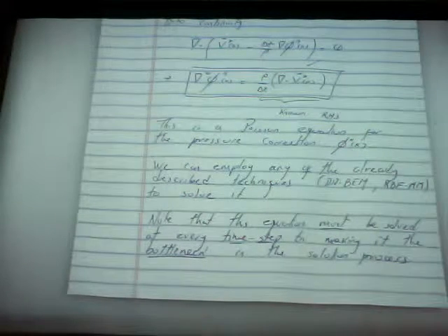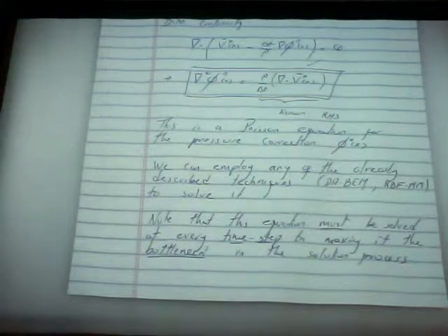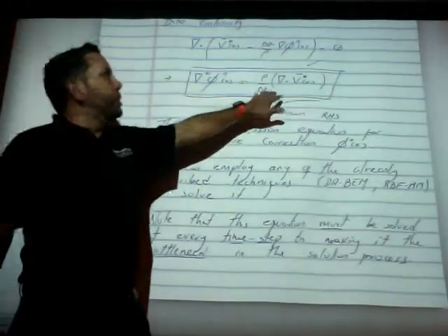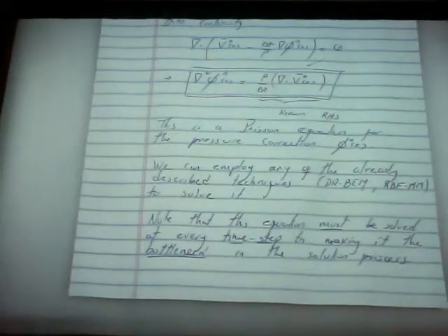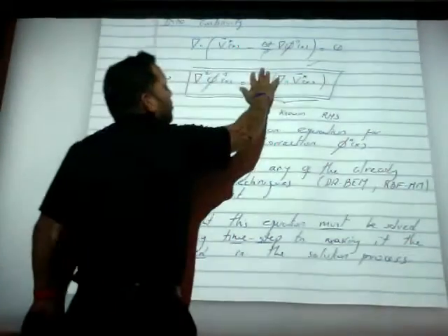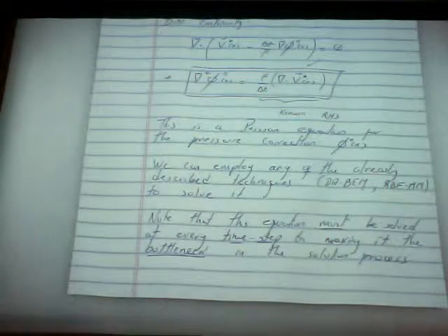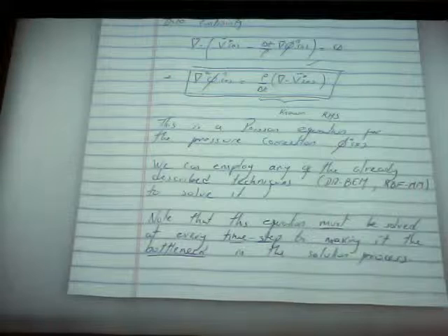You have to do it with boundary elements or with meshless methods. You have to form a collocation matrix or an influence coefficient matrix, apply boundary conditions. And why do we need to solve it again and again and again? Because the right hand side changes. This is continuously changing. The V star changes at every time step because we're advancing it in time. So the Poisson equation kind of remains the same, but the right hand side, the forcing term, changes. So this is the bottleneck of every CFD solver. That's why CFD solutions are very slow. Because at every time step, you have to solve a full problem, a full Poisson equation.